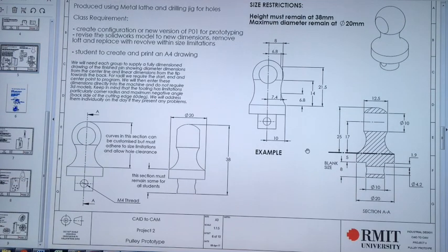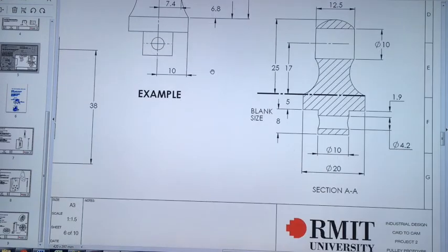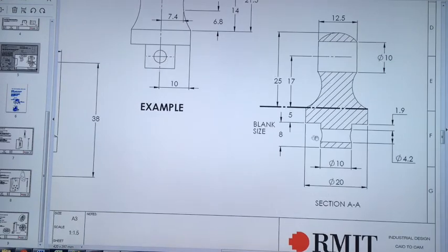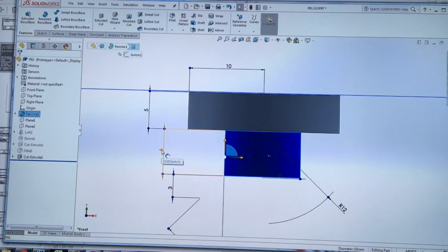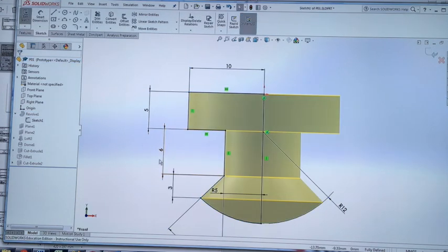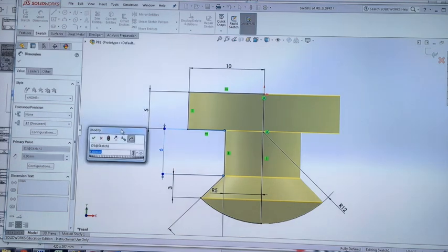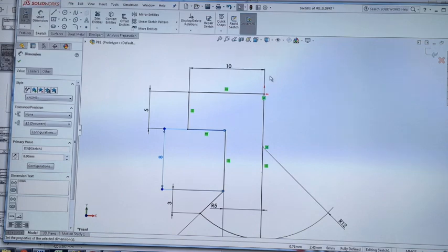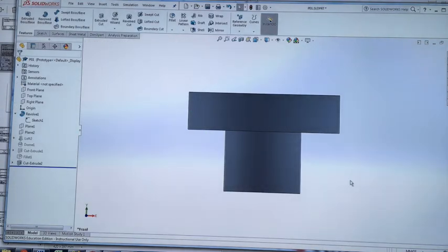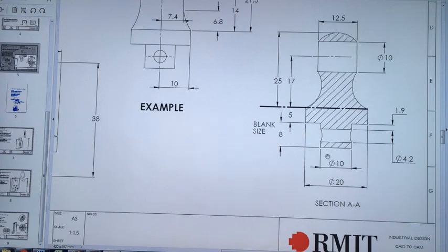So on the bottom, I want to get it looking like this here. So it's going to have a height of 8 millimeters. At the moment, you can see that it's 6. So this is one part that we can change in this original sketch. So I'm going to edit the sketch, click on that dimension there of 6, link it to this configuration, change that to 8. Press OK. Later on, we'll come back and cut the hole.